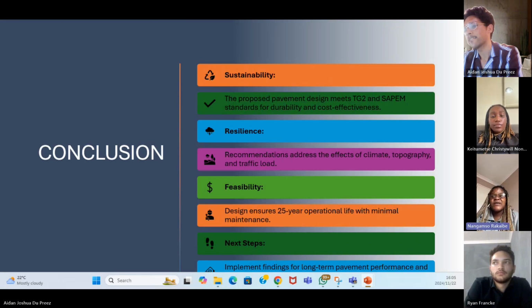Subgrade performance: the subgrade layer exhibits significant variation in strength, while the upper layer, which is layer 1, provides adequate support with a CBR value of 53%. Deeper layers, 2 to 6, have a lower CBR, which indicates stabilization methods such as lime, cement treatment, or any other relevant stabilization method.